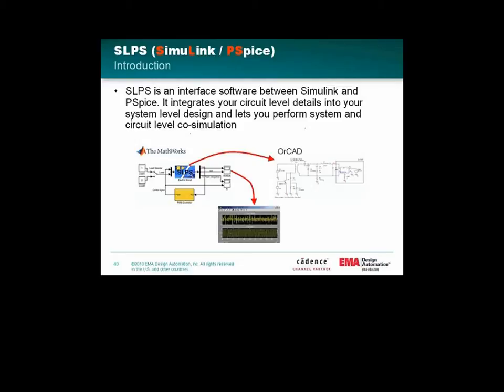Simulink is kind of the master. At every time step, it's calling for PSpice to solve its portion of the circuit and pass that information back. So they walk together and do co-simulation. That's really powerful if you have control systems or something designed with Simulink and you want to put some real circuit intelligence into there from PSpice, as opposed to the more ideal stuff that Simulink would come with. It's a really good pairing. Simulink is a very strong control system tool, and doing stuff like that can be very useful. So that's a tool that we offer.